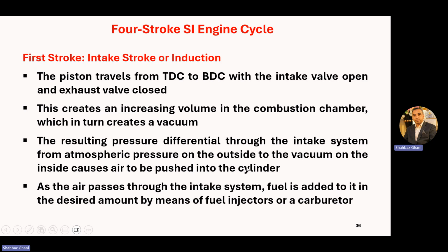When piston is moving from TDC to BDC, it's creating a large volume. Large volume is creating a vacuum. To fill that vacuum, we have a pressure differential and intake valve is open, so air from the atmosphere will rush into that vacuum to fill that vacuum and that volume.